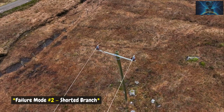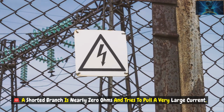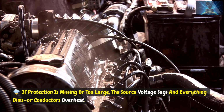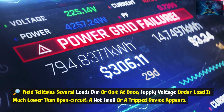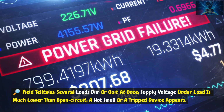Failure mode number 2. Shorted branch. A shorted branch is nearly 0 ohms and tries to pull a very large current. With correct protection, the branch, fuse, or breaker trips quickly. If protection is missing or too large, the source voltage sags and everything dims, or conductors overheat. Field telltales: several loads dim or quit at once. Supply voltage under load is much lower than open circuit. A hot smell or a tripped device appears.